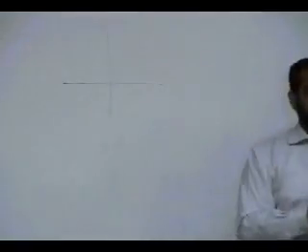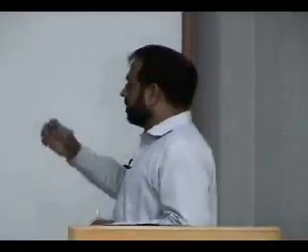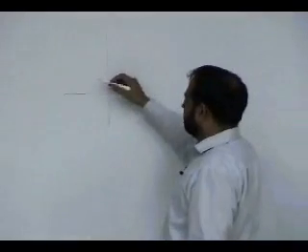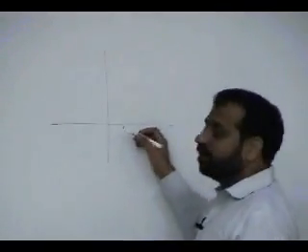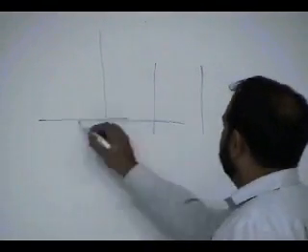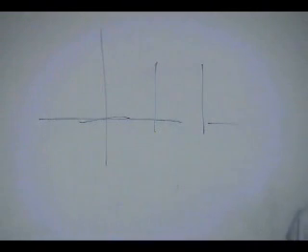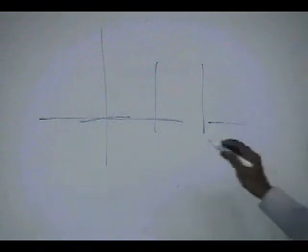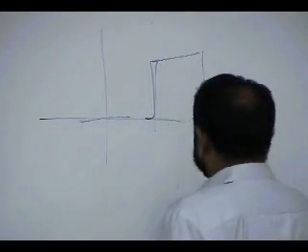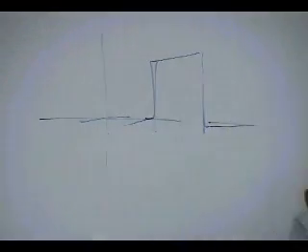You can always compare the deterministic versus the adaptive. What is the difference? Deterministic is against something which is known to you. I have given you this example several times. If you are designing a satellite receiver, you precisely know this is your band and everything which is not your band is out of band noise. So you want to throw that away, so you design a deterministic filter. This is deterministic signal processing.